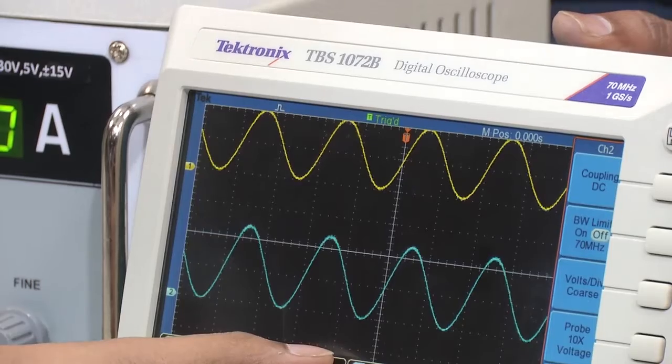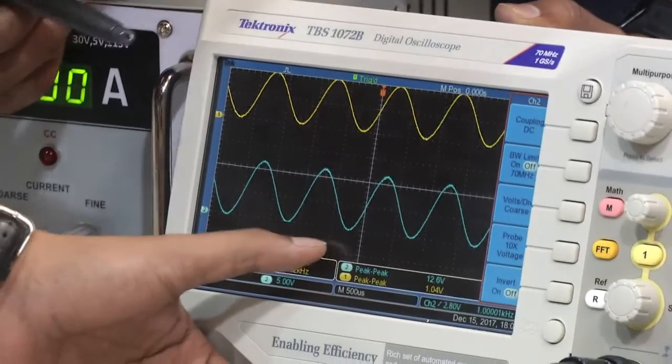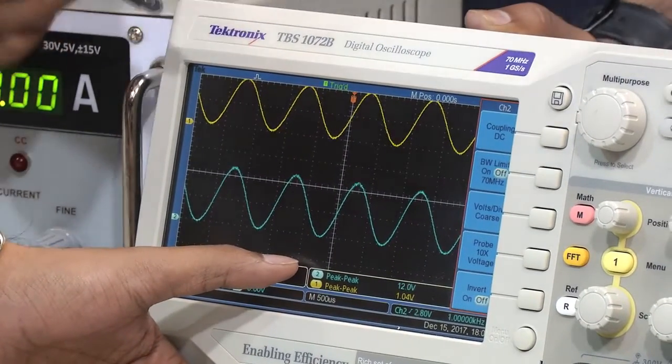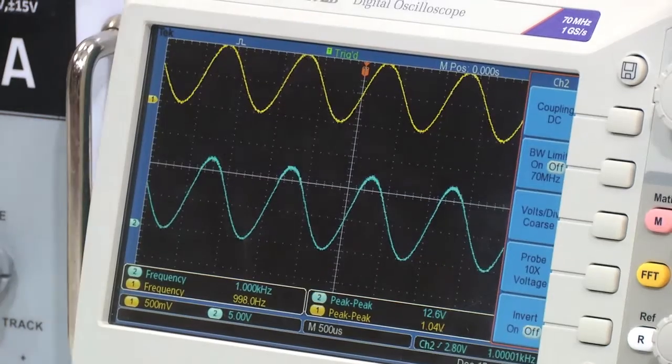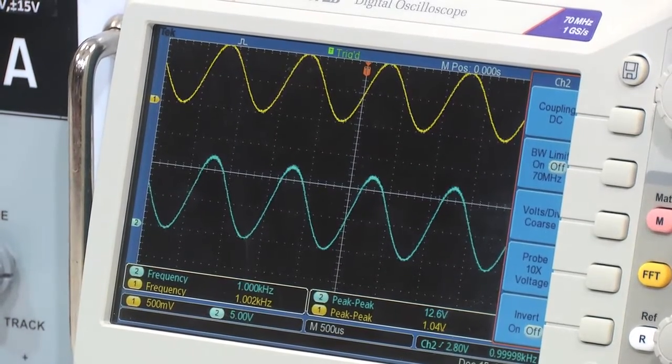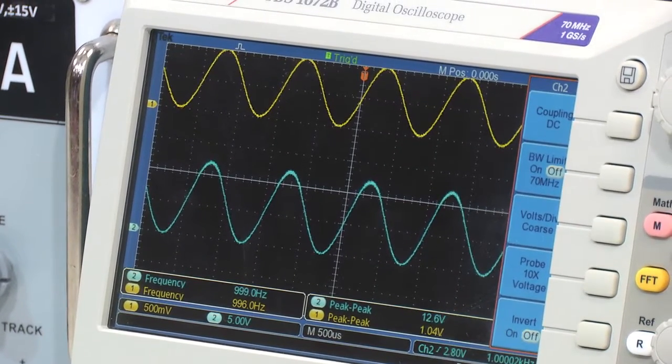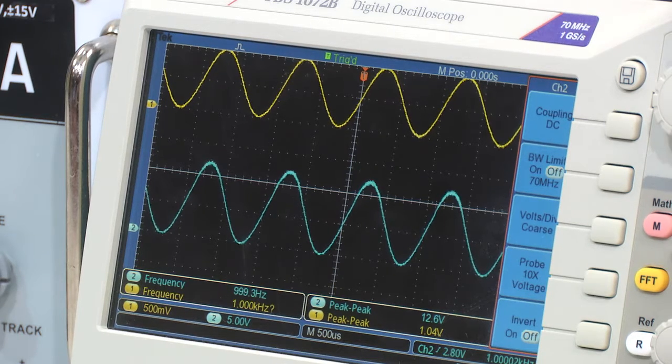it is difficult for me to see. So, I cannot tell, let me see, it is about 12.2 volts, alright, 12.2 volts, yeah, now it is better. So, around 12.6 volts, right. And our input of 1.04, we are getting output of 12.6, still it is not clipped. Why? Because still the output signal is less than the bias voltage. Now, let us see if we increase it by another 0.5, that is from 1 volt to 1.5 volts.